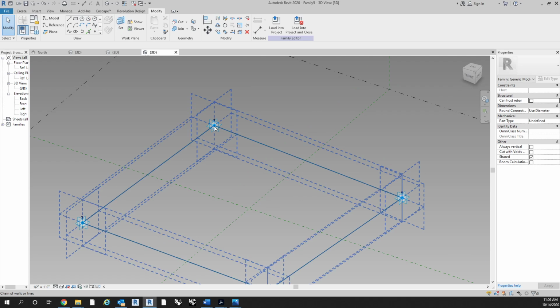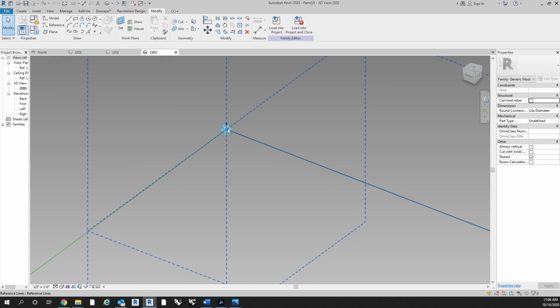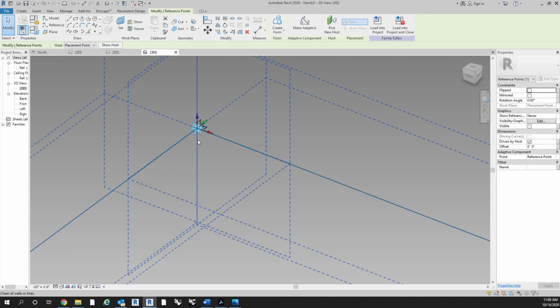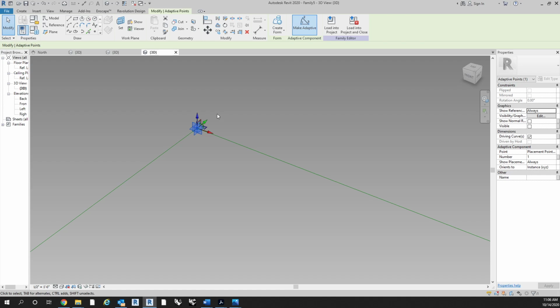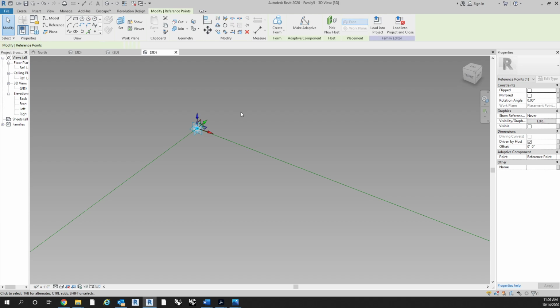So if you tab in, of course I had it, there we go. So make sure you select the point. If you are selecting the adaptive node, all 3 planes are going to highlight. So make sure that you tab in and grab that point. And then over at the right, underneath the properties, there's an offset parameter already set. And what we're going to do, so let's just first change it to, let's say, 2 feet.